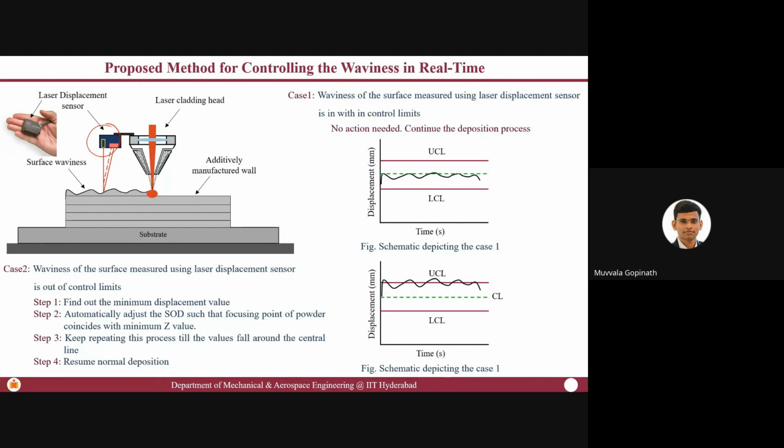It can talk about surface roughness in your machining process, and based on the surface roughness, it can tell about your tool life condition. Is it just that? No, it can be used in cladding. Again, if you look at your IR parameters, is it only used in additive manufacturing? No, it can be used in casting, welding, machining, anywhere where heat is involved, which acts as a signature.